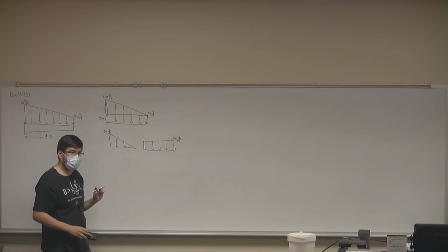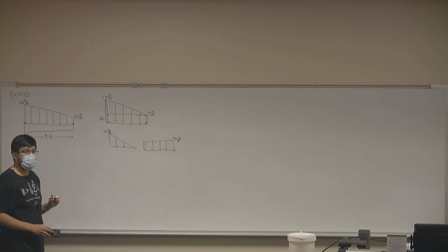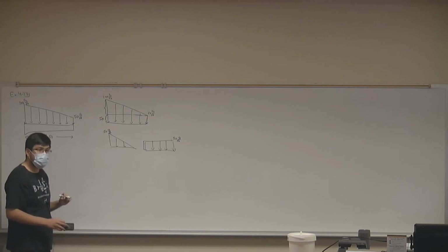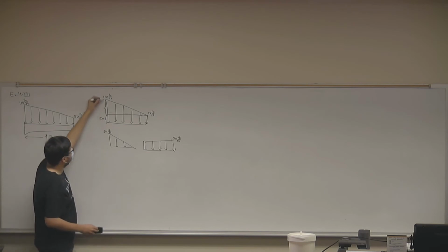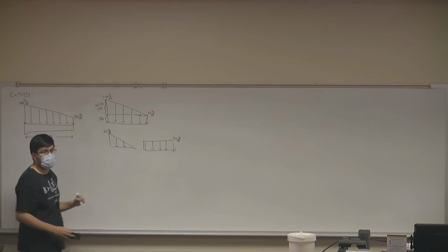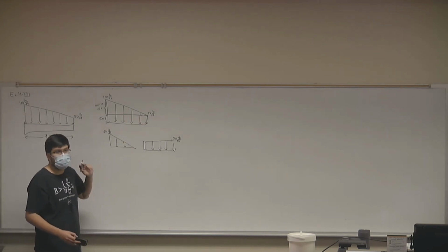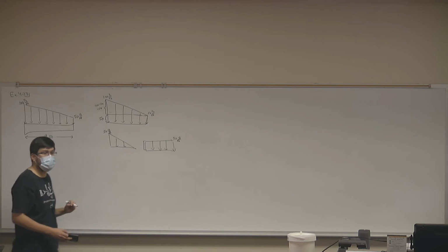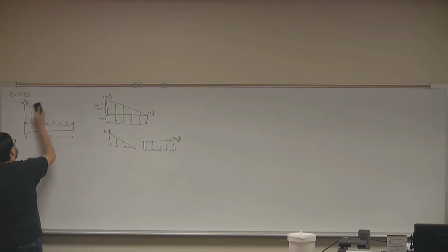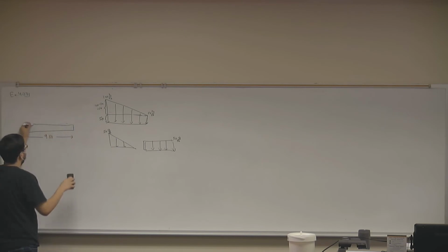So I should think about it less in terms of which is on the right and left, and more about the height of where they put the force. Yep. So this is 100 minus 50, or just 50. Okay? And of course, this is just 0, because that's where our triangle starts. Okay? Good. So we've broken down this trapezoidal load into two loads, a triangular one and a rectangular one.